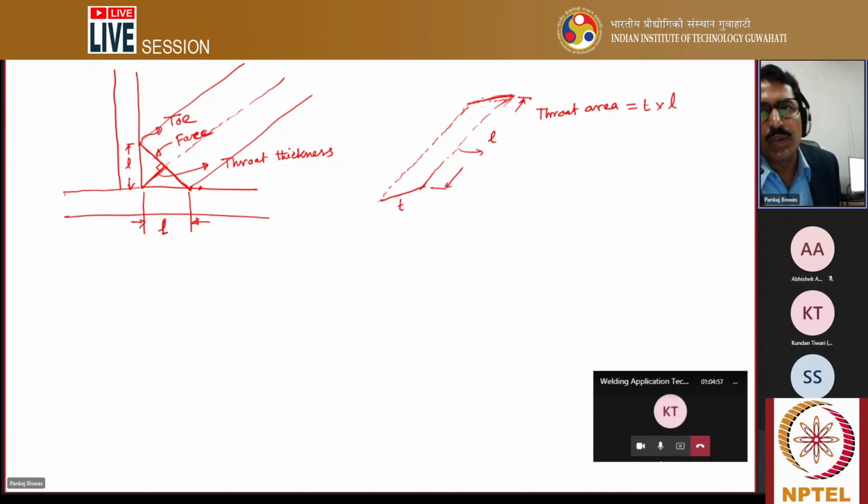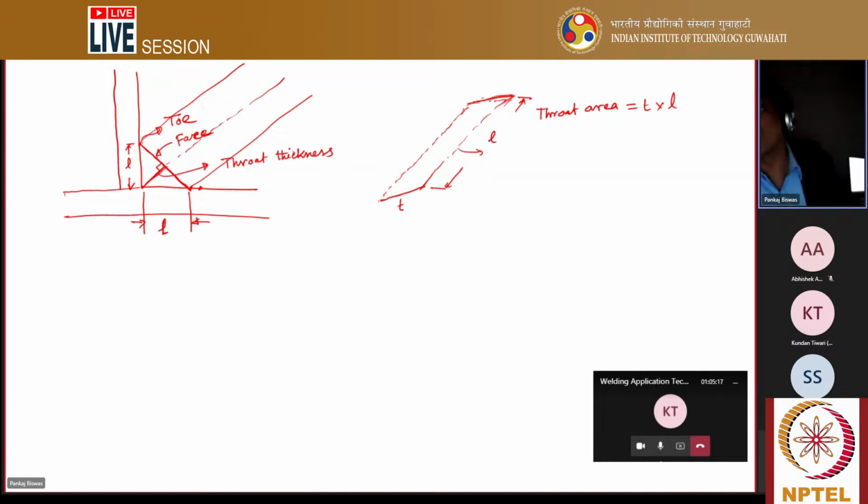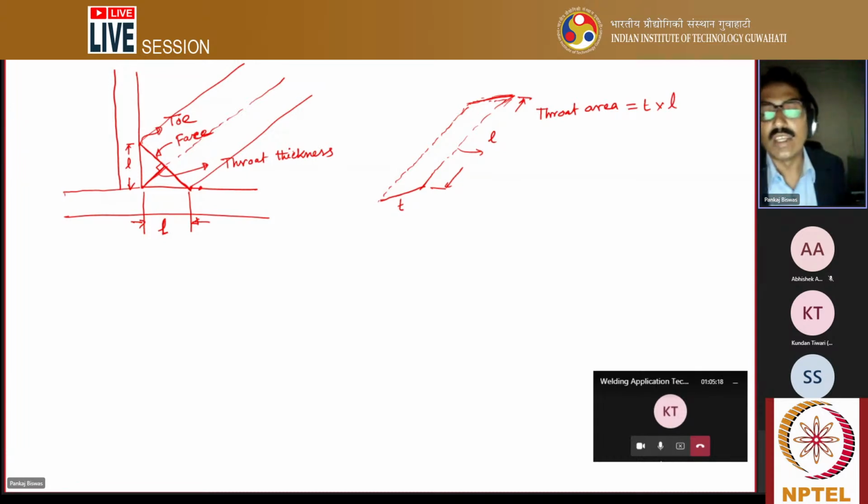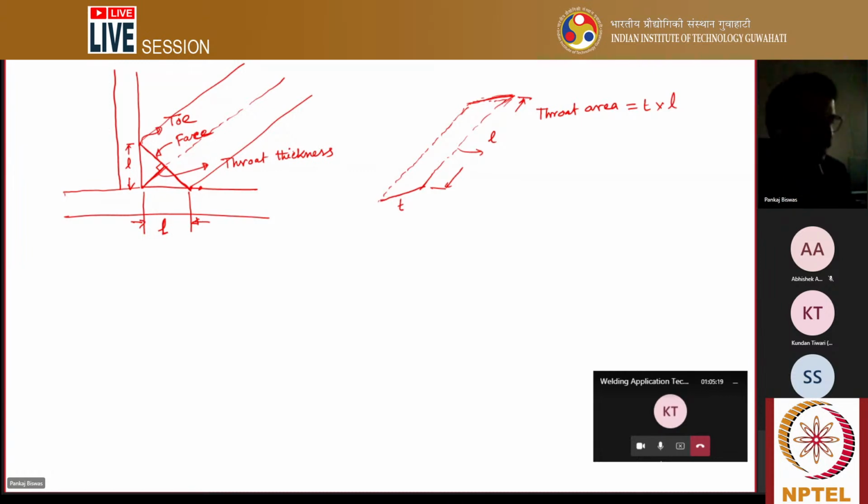If the electrode is more heated, definitely degradation of the electrode will take place. That's why frequent cleaning and other things are required for the welder. So if you can reduce that wear or excess heating of the electrode, you can definitely reduce that.